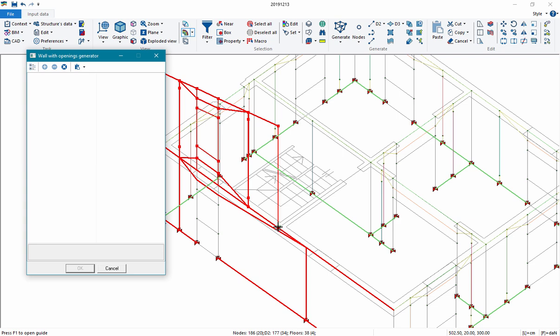Okay, in this case we are lucky because we have an intersection with an orthogonal wall just in the middle of the wall, where we have the longest height. But if we don't have an intersection with an orthogonal wall or other structural elements, we anyway have to divide the modeling into parts.